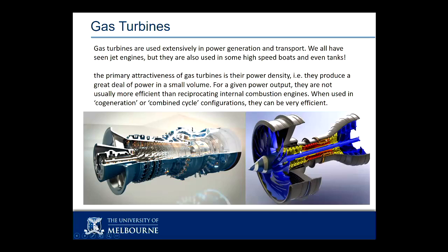In this guy, these are compressors. This guy here is where the combustion's happening, again as an annulus. And then I've got turbine, turbine. Here I've got turbine, turbine, turbine. I usually have many more compressor stages than I do turbine stages. But for the thermoanalysis, we treat them as one thing. Even though the compressor is made up of many, many fans, squeezing the air down and down and down, we treat it as one thing for now. And the turbine we treat as one thing as well.